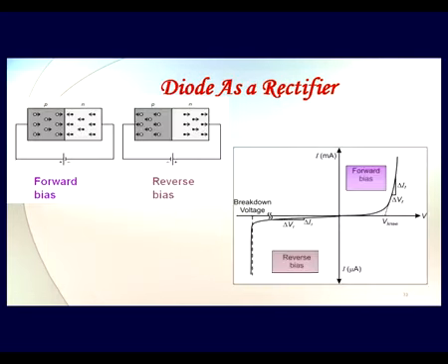And here I am showing you the current voltage characteristics of a diode, where in the left hand side figure we have connected the positive terminal of our supply to the P terminal or anode and the negative to the cathode or N terminal. Then this diode initially has a slowly increasing current, but as soon as it reaches its knee voltage, as it is called, then it just shoots up.